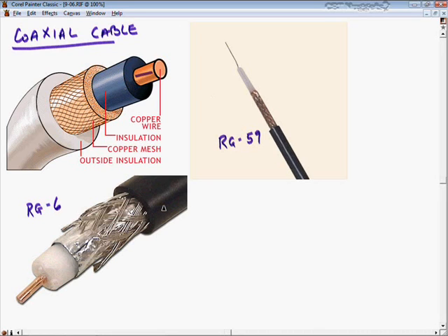Now, for proper functioning, coaxial cable has to always be terminated at both ends, and the outer conductor grounded at only one end. Termination is achieved by connecting the inner conductor to the outer conductor by using a resistor of a certain size. Many terminators have a grounding wire which can be connected to an earth ground, like a water pipe, for example. Now, the size of the terminating resistor is measured in ohms, like 50 ohms or 75 ohms or 93 ohms. And by connecting the inner and outer conductors with the terminator, you complete the circuit for electrical signals to flow in the cable. If one or both ends of the cable aren't terminated, there's no electrical circuit and therefore no data communication.